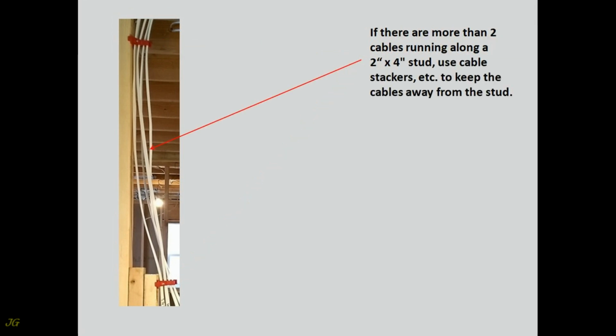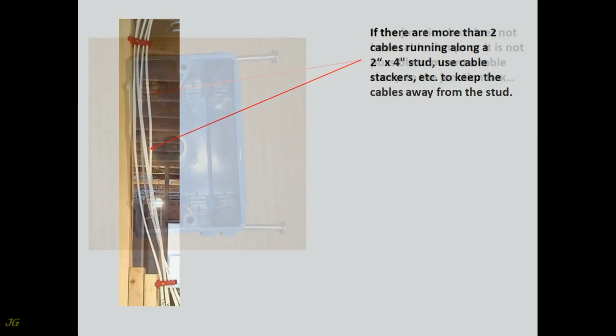If there are more than 2 cables running along a 2 by 4 inch stud, use cable stackers, etc. to keep the cables away from the stud.